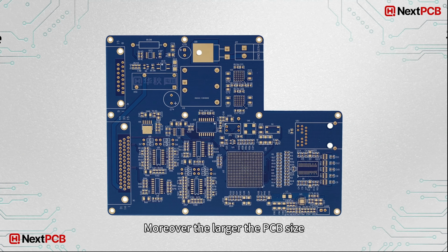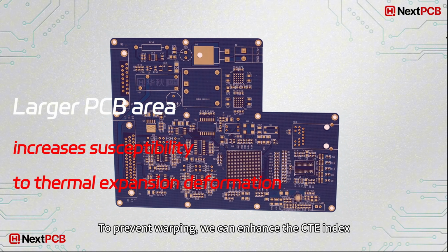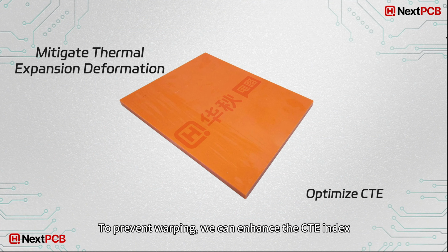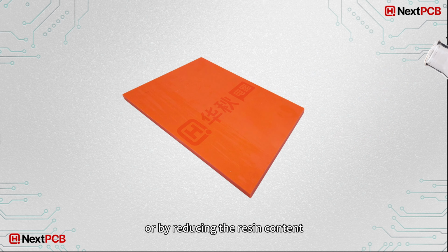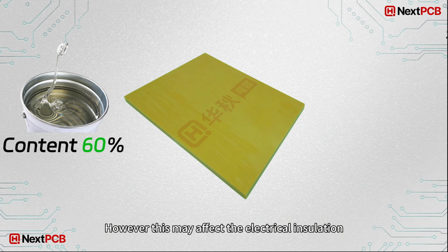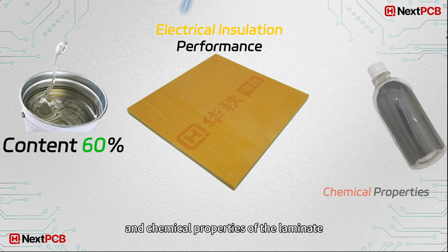Moreover, the larger the PCB size, the more likely it is to warp during reflow soldering. To prevent warping, we can improve the CTE index by modifying the resin in the laminate, or by reducing the resin content. However, this may affect the electrical insulation and chemical properties of the laminate.